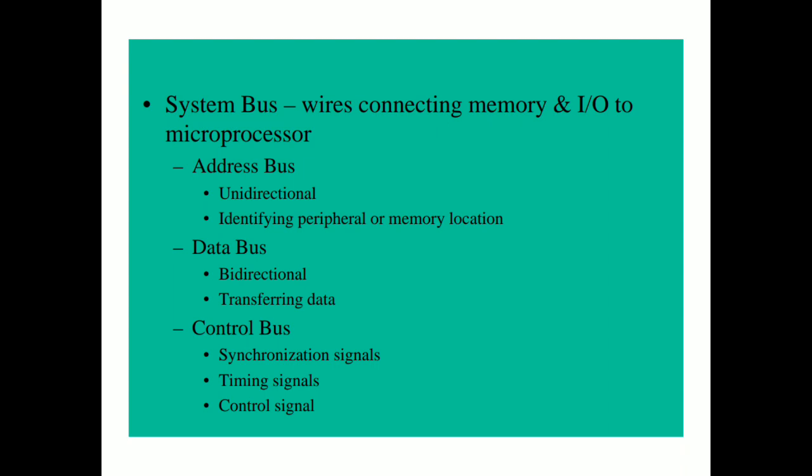This means that the output of the program counter addresses a specific register in the memory. The width of the address is decided by the designed memory addressing capability of the CPU. That is, the width of the address bus will be equal to the width of the program counter.